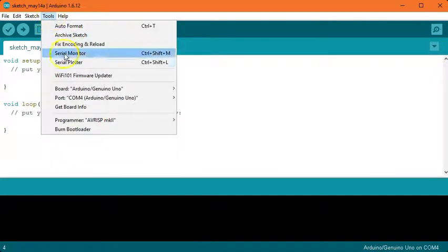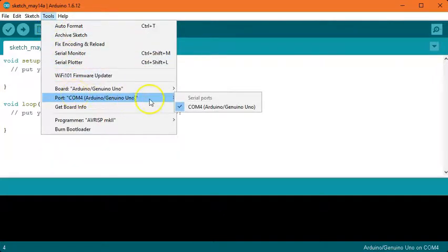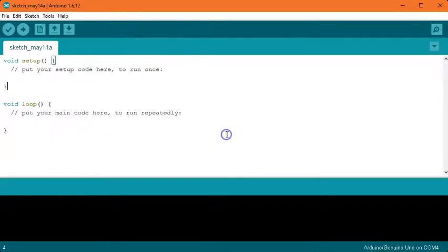And the next thing is then to select a port. And sometimes this will select automatically for you, but make sure that once you have that kind of squared away, that port comes up here and that it reads your board when it's plugged into your computer. You can check that also down here in the lower right. It says that it detects an Arduino Uno on COM4. And we will need that COM port when we go into processing in a minute.